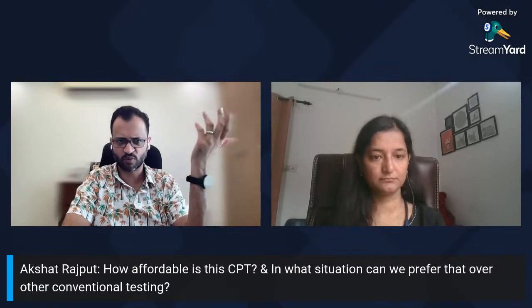And in what situation can we prefer CPT over conventional testing? Really, you have to design this. If your site has rock, CPT is not a good solution. You have to go with other test methods such as boreholes. If you are anticipating soil, and soft soils primarily, then I think CPT is a very good option and should be explored.